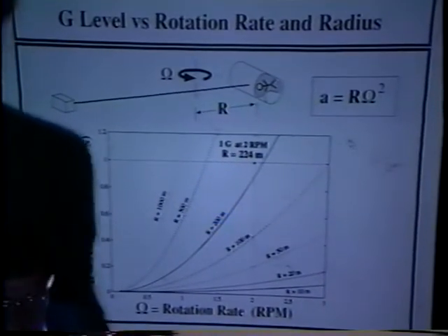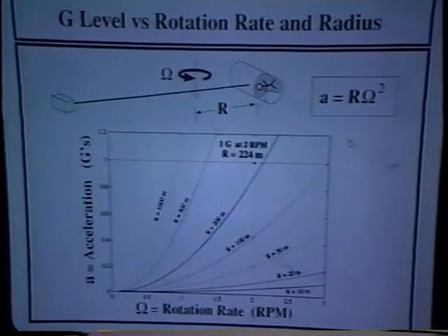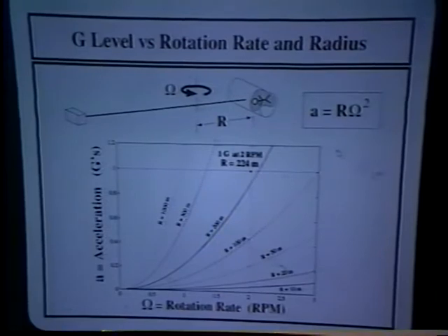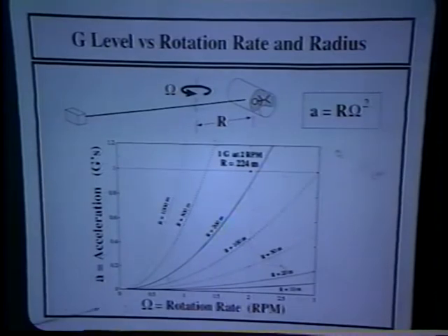There's some uncertainty about the fastest rotation rate that would be comfortable for the inhabitants of an artificial gravity spacecraft. But it's generally agreed that 2 RPM or less is slow enough that motion sickness is not induced in the occupants. There is the possibility of adaptation to higher rotation rates after a considerable length of time.